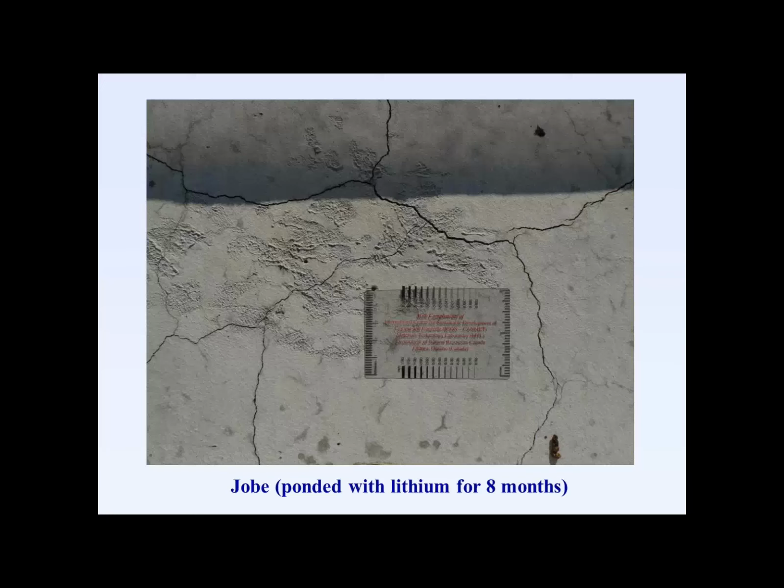But there will be cases where the expansion may exceed the capacity or the elasticity of that steel, or where the concrete beyond the reinforced region, the covercrete, is cracking so considerably that the concern becomes chloride or water going through the cracks and reaching the steel. So the idea would be to provide additional external restraint that would envelop the entire structure and thereby protect it from the elements, and also provide the external restraint.